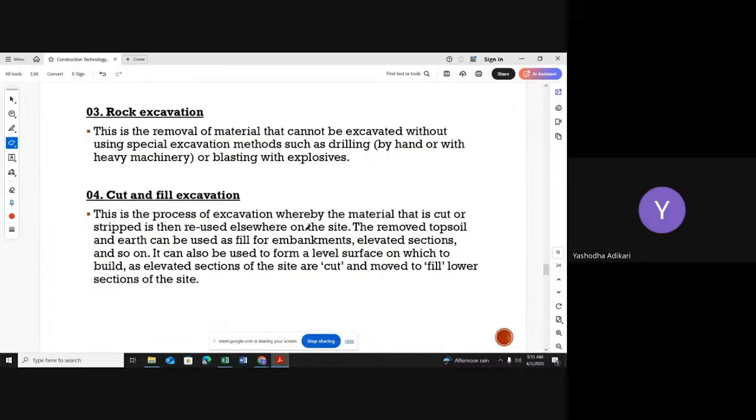Normally, to identify excavation depth under the dredging system, we are using a sounding system. That is the method to measure the excavation depth. A sounding system means we release a sound wave. We are checking the reflecting time. We measure the time it takes to go, hit the soil, and reflect back.